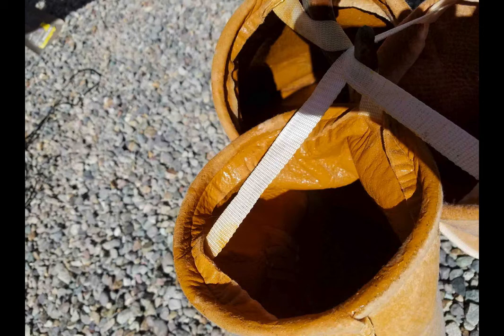This is what the bag filters look like in your bag pots. The solids coming through, you can see it's just kind of a felt. They've figured out a few different materials that seem to work better than others. And I want to say this one's rayon coated. And so here you can see it's just a large flow-through filter. You can move a lot of water through it. It's not like you have to cram it through like you do a membrane. And you grab those dissolved solids that are transitioning to suspended solids out right here. You open the bag pot up, you pull it out, you let it hang out and dry. And these are the solids that we were forming.